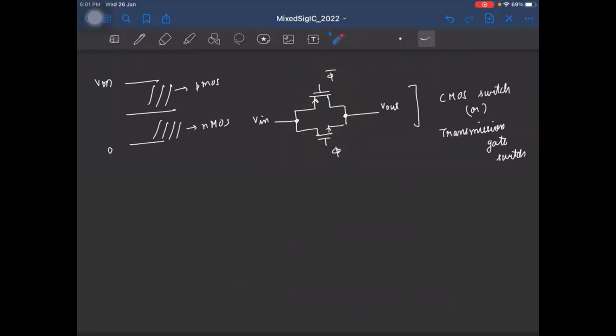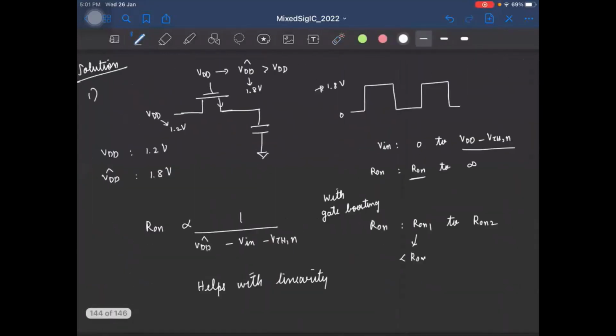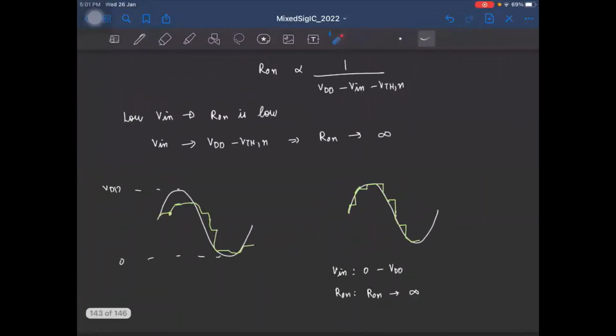Similarly, when the input voltage is high, closer and closer to VDD, the NMOS will offer an infinitely large resistance and will be out of the picture, and we'll have conduction through the PMOS, right? This way we have a reasonably good switch over the entire range. Even intuitively, we expect that the distortion we saw with only an NMOS switch must now be better.